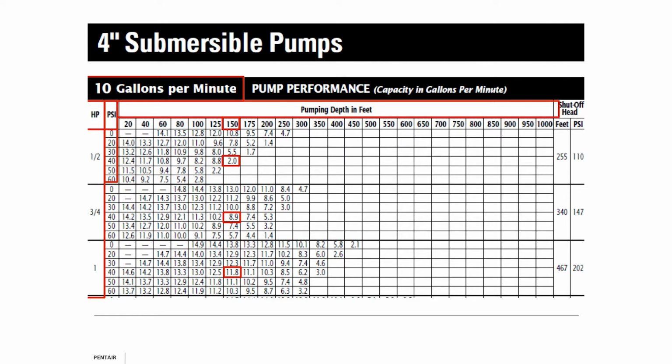Okay? This is just to emphasize, not that I'm trying to be nitpicky, but this is how people get tripped up. We've got to make sure we understand the language and what we mean when we say these words. When you told me total dynamic head at 154 feet and 40 psi, you just said, oh, wait a minute, I don't have total dynamic head. So that's where we have to be careful. That's where sometimes customer service agents will pick apart the numbers.